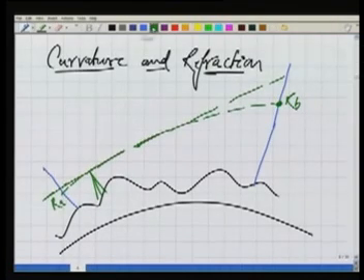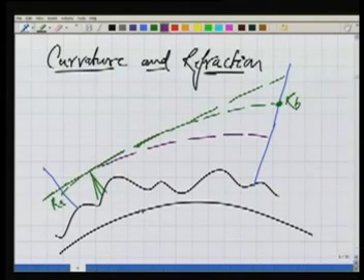In the ideal case, I should have observed along a surface which is the level surface, parallel to this surface. So that would have been something like this, parallel to that. But we cannot establish this. We know it already. We have seen the effect of curvature and refraction.